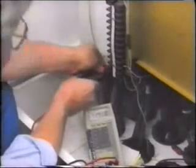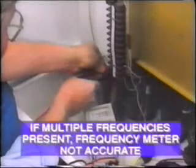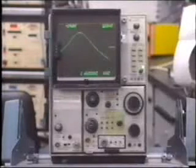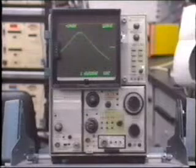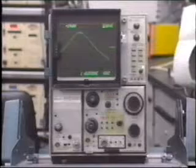We often need to measure signal strength at a specific frequency. If multiple frequencies are present in the signal, the frequency meter will not measure accurately. In this case, a spectrum analyzer may be used to examine the signal across a wide frequency range so as to detect the presence of unsuspected additional signals.